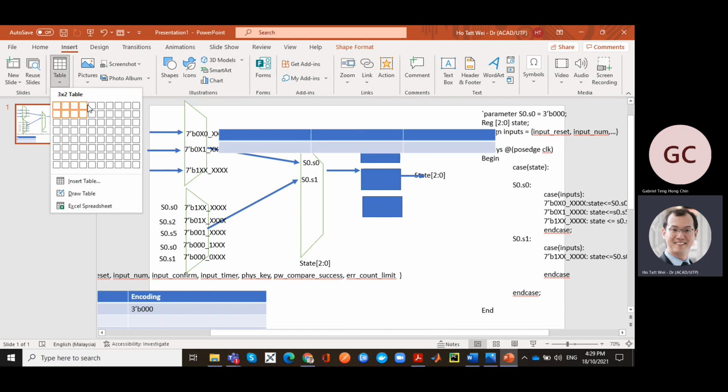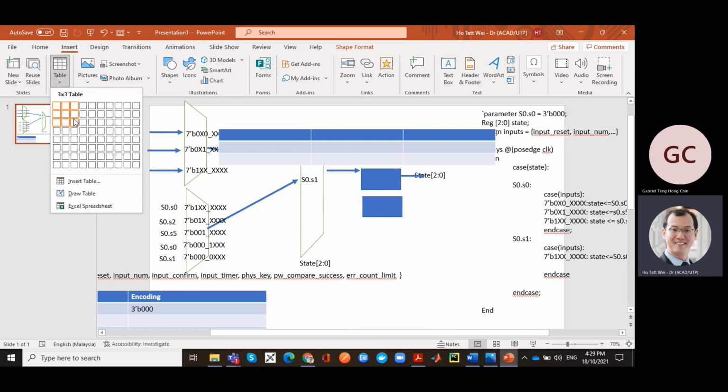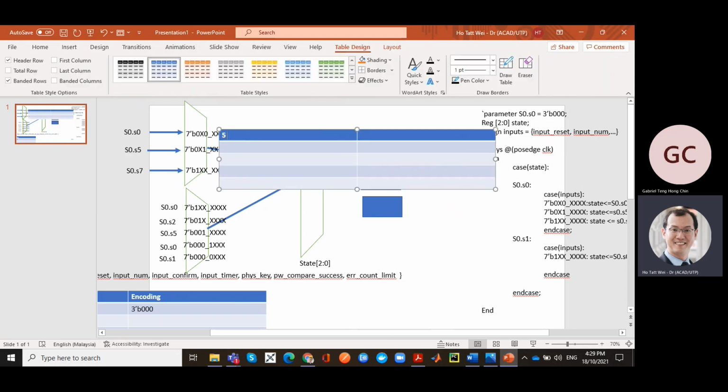You're basically trying to specify these output bits as a function of how many bits? 3 state bits, 2 bits, right? So you have a 5 input truth table. You are specifying 5-bit inputs, and the output is 3-bit output because you're specifying states. So your 5-bit inputs here are basically, I'm looking for the state 0. I'm talking about this one first.